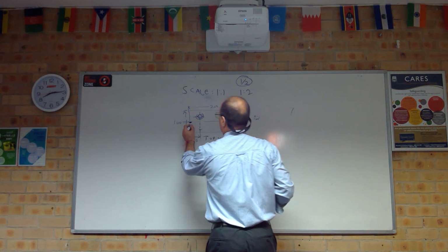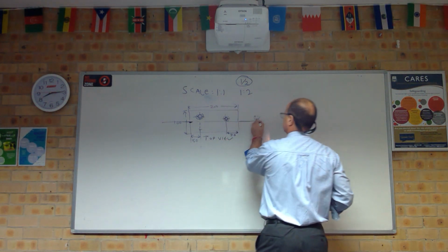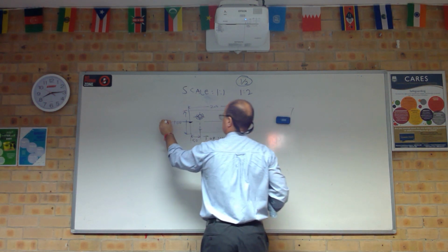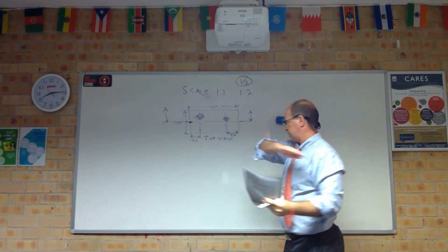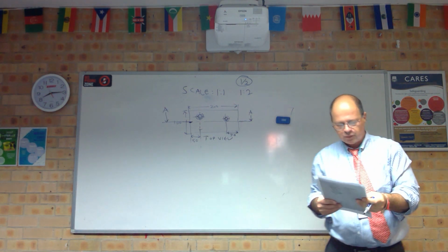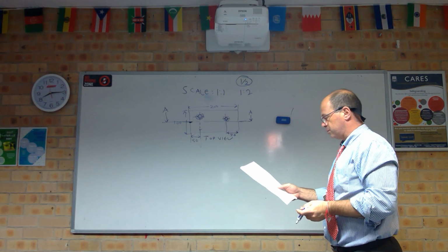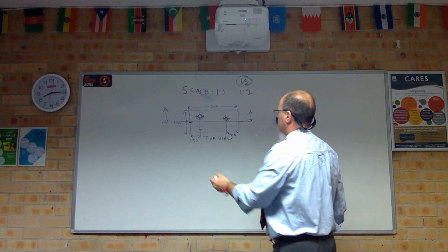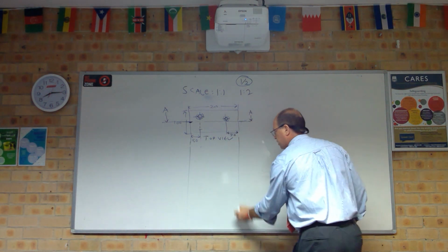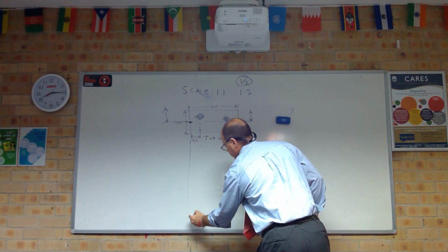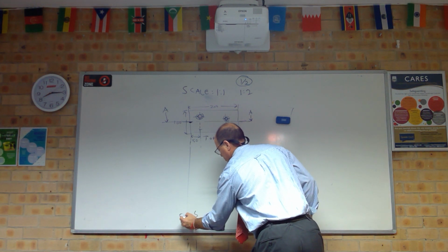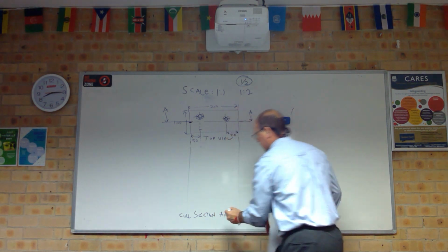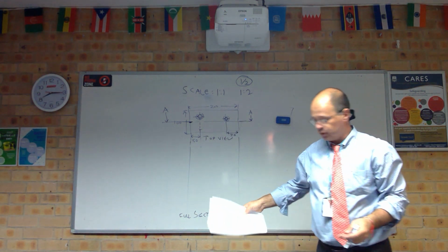And so we're going to do a section line through here, okay? So what's the section line? A. So that is where we slice our block, okay? Then now draw a full section of this block below the top view showing its thickness and the tapped holes we created. So you can draw guidelines down from this top view, and this is going to be section, full section, AA, okay? So you're going to draw that section below, okay?